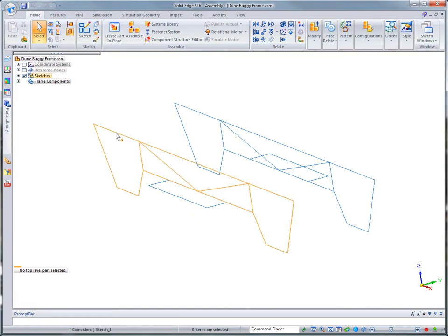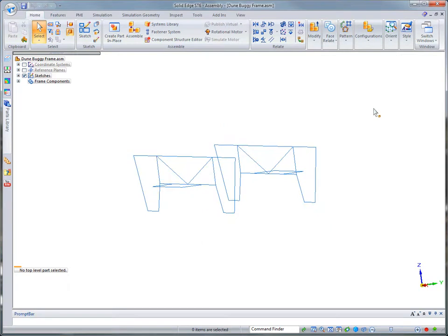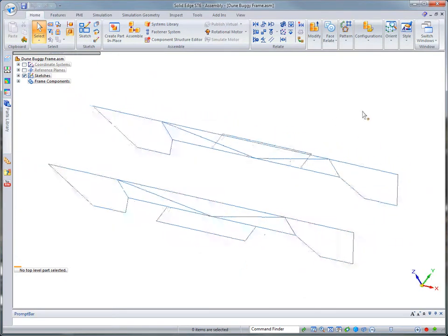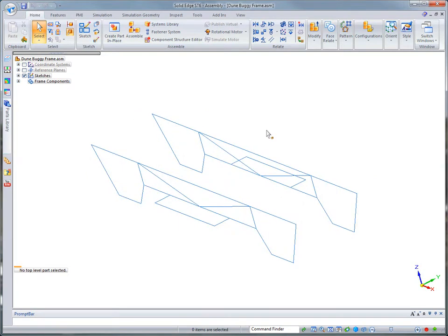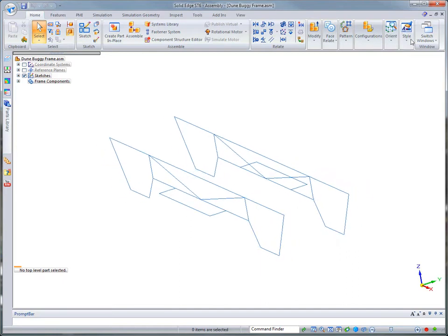From the assembly level, we went into the sketch environment, created a side face, and then we offset the reference plane to create the opposite side and copy these sketches to the opposite side just to get the width. And then from another view, we also added these side sketches. And from that, we went into the frame environment and created our frame, but we had to add the lines between the corners all the way around this part so that we could create the full frame.